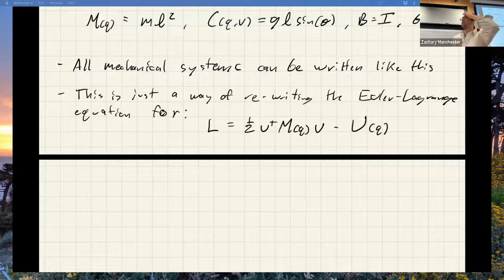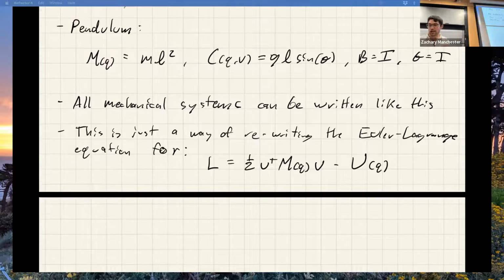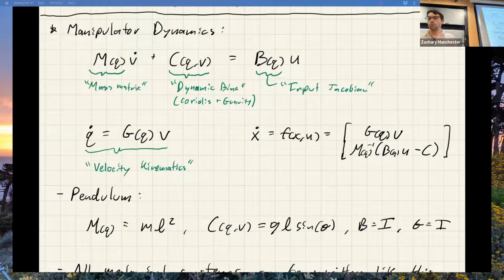which can be anything, right? So really, it's just assuming that your kinetic energy looks like that, where that M is your mass matrix, which is true for any mechanical system, any kind of robot. Yep. Are we accounting for the damping forces or non-linear forces in general? So those show up on the right-hand side as additional forces. In general, you'll have another generalized force input F. I should have probably written that. So this would be external forces.